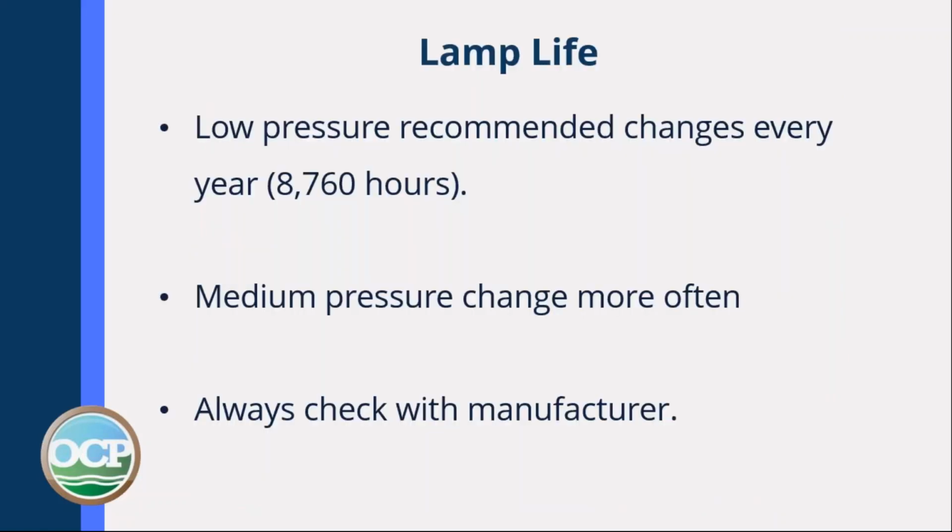Lamp life: low pressure lamps, it's recommended you change them every year, so that you have enough energy going into the cells to destroy the DNA. You need to follow the manufacturer's recommendation. Medium pressure lights get changed a little more often. Always check with the manufacturer of the system that you're using.